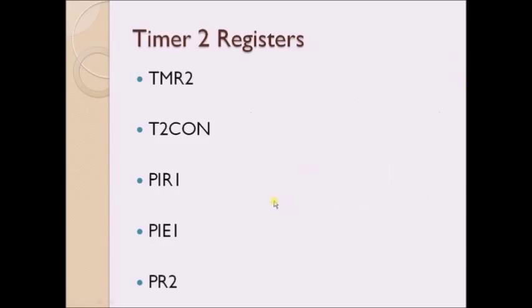Now let us see the timer 2 register. If you want to use this timer 2 peripheral, then we have to access these registers like TMR2, T2CON, PIR1, PIE1, and then one extra register, that is PR2.